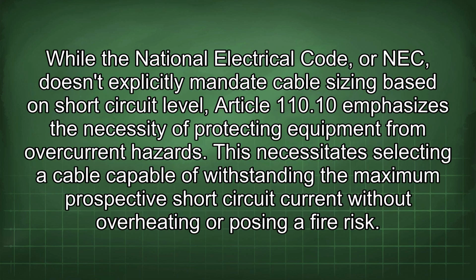While the National Electrical Code, or NEC, doesn't explicitly mandate cable sizing based on short-circuit level, Article 110.10 emphasizes the necessity of protecting equipment from overcurrent hazards. This necessitates selecting a cable capable of withstanding the maximum prospective short-circuit current without overheating or posing a fire risk.